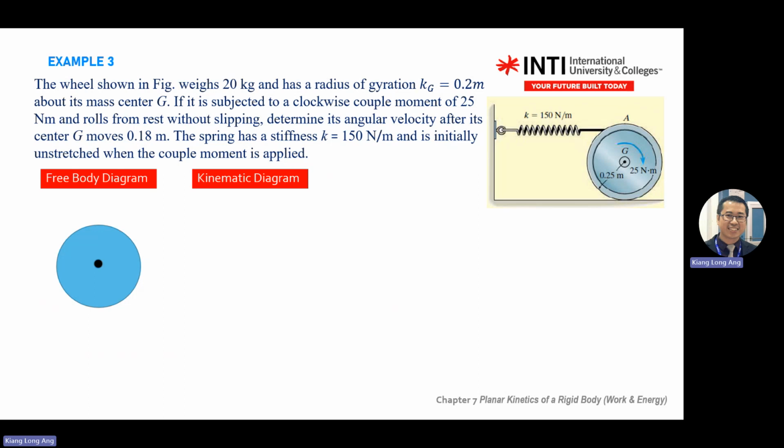There's a contact force, friction force. Right, so this one you rotate clockwise, subject to a clockwise couple moment. It turns this way. Where is the friction force? You rotate this way. You go against the motion. Okay, it's like rotating like this. Yeah, the friction will stop the motion. So the motion goes this way, I mean this surface goes this way, so the friction goes this way.